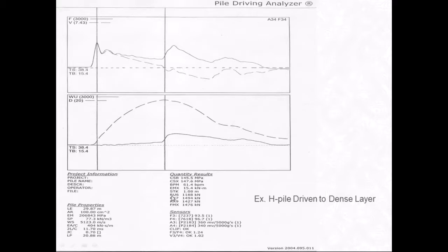And then down here, these R values, RX7, are different capacities for different soil damping factors. And this is going to tell us what we have for an estimated capacity in the field. So that's where we come up with, I mentioned earlier, we typically come up with a range of what the capacity may be depending on the soil conditions.